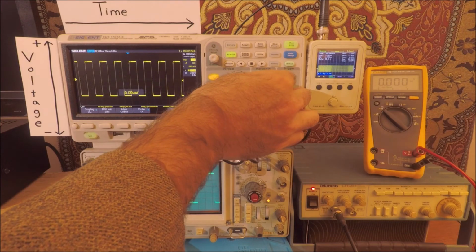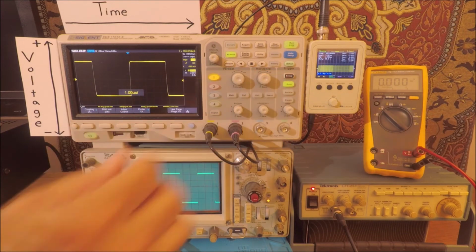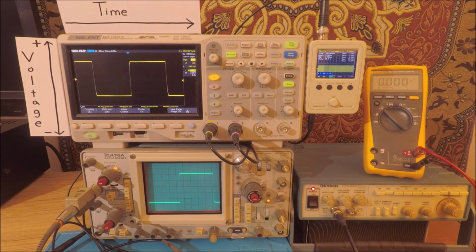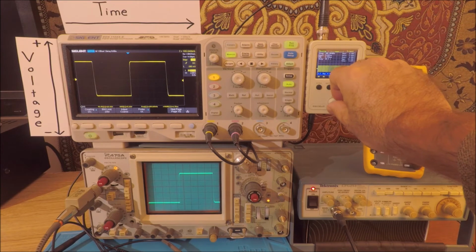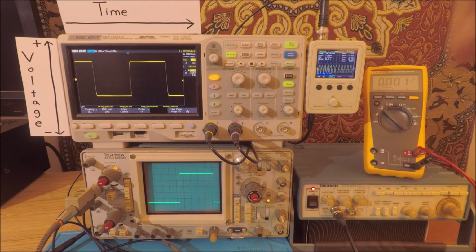We can do the same here. And we can see a fairly nice square wave on these two scopes, and we can do the same over here. But that's interesting. Notice how on our portable oscilloscope, we're not seeing a nice square wave anymore. We're actually seeing a sinusoidal wave. So at 100 kilohertz, we have exceeded the bandwidth of our small, affordable, portable scope.